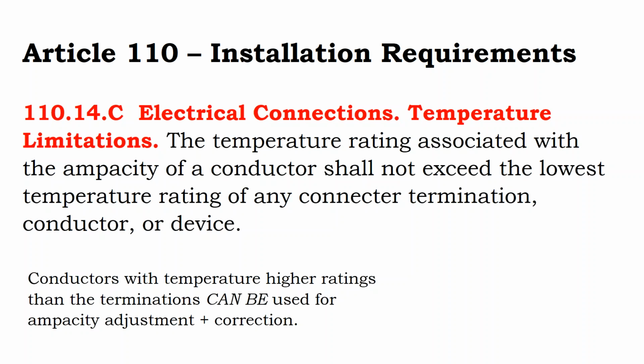It's rated at a lower temperature rating, and that might be all right. You may never get up to that higher temperature rating on your rooftop anyway, so it may be perfectly appropriate for you to use that disconnect switch on top of that rooftop. And what we learned in other classes is that if you don't know what your rooftop temperatures are, you can always go to PVWatts, and inside the hourly temperature data in PVWatts, it'll tell you what your ambient rooftop temperatures are.